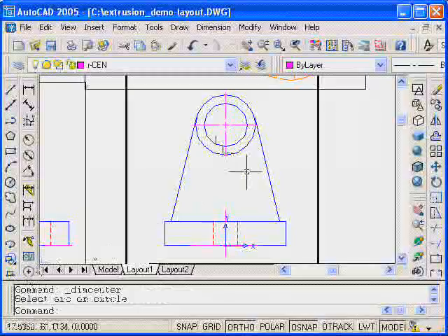Now I'm almost ready to add dimensions. Before I do, I will lock the viewports. I will do this to avoid altering the view scale. Whenever a viewport is active, it is easy to change the scale using the zoom command. If I use zoom right now, the scale is no longer the same, and this view is no longer aligned with the one below. Now I'll undo that,